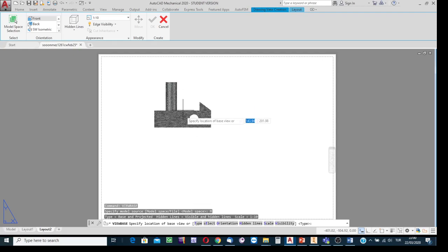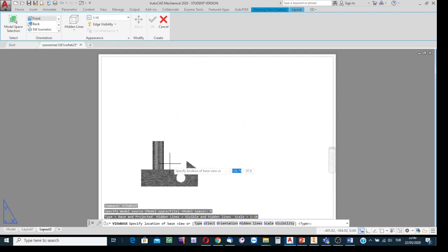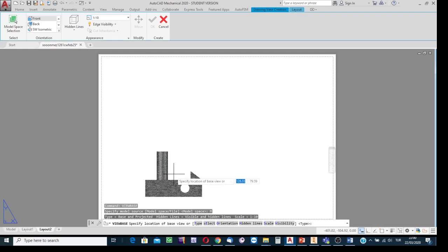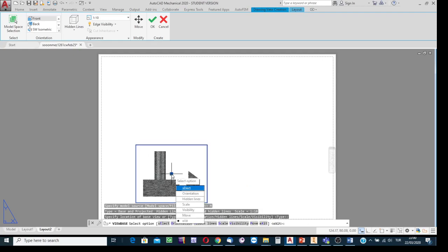And then yes, this is the front view in the simulation. I know that in the third quadrant, front view is created using this pad of paper. With a click, locate it, and then say exit. If the orientation is wrong, select orientation option and change. If the scale is not so good, then select scale option and then change the scale factor. You know such things. If the orientation is correct, if the scale factor is suitable, then click on exit button.